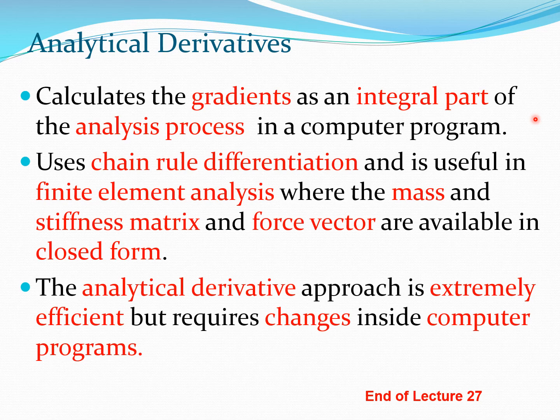And somewhere you will have some lower level functions where you have explicit coding of the different parts of the matrix or the vectors. This coding would be explicit in terms of shape functions, the stiffness of the structure, the density, and cross-sectional properties sometimes, etc.